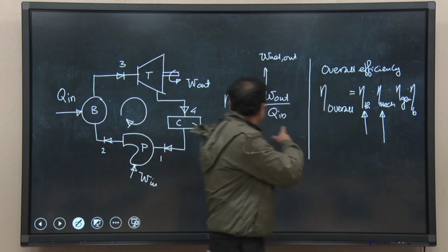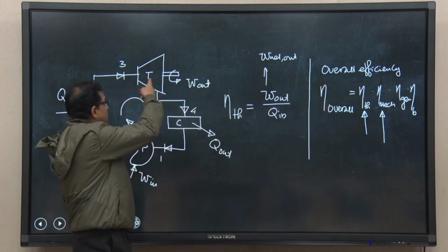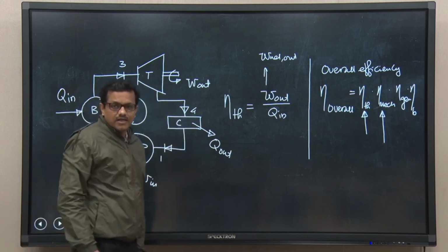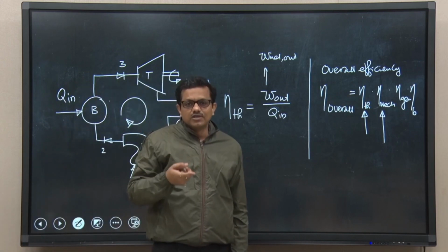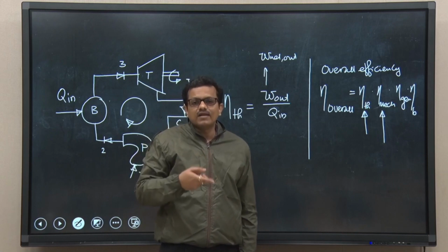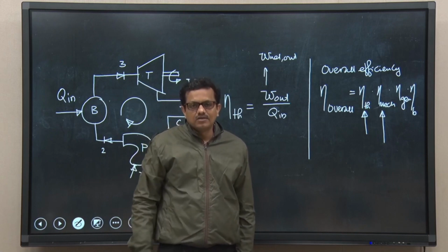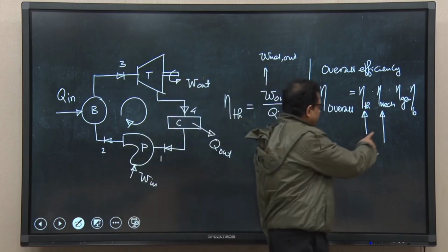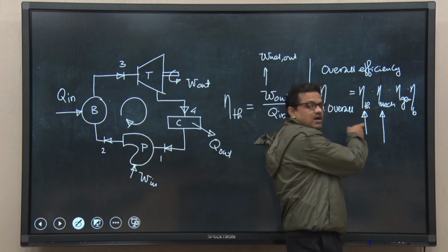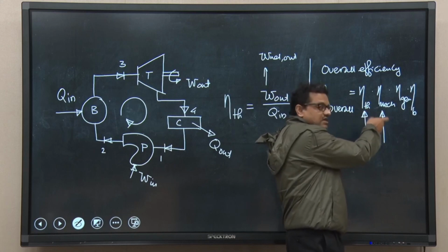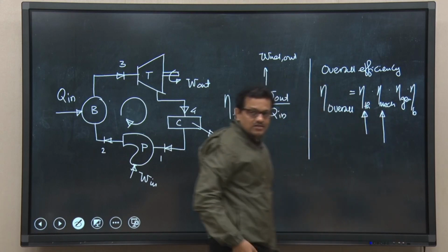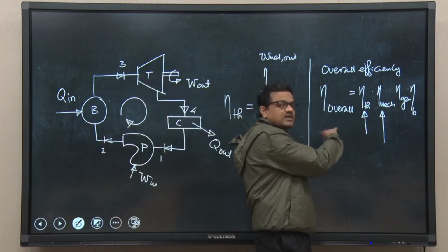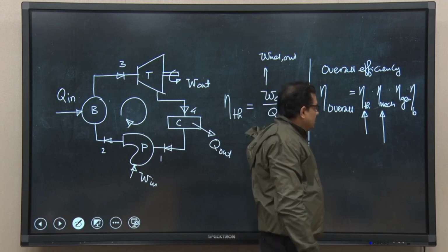So, when steam is flowing through the turbine, it does work on the rotating part of the turbine. So, energy is produced, but that energy is not available at the shaft of the turbine because of some mechanical losses, and that is why this mechanical efficiency is coming into the picture. So, we have talked about the thermal efficiency, we have now discussed mechanical efficiency. As such, I am discussing why, because you should know why overall efficiency is important.